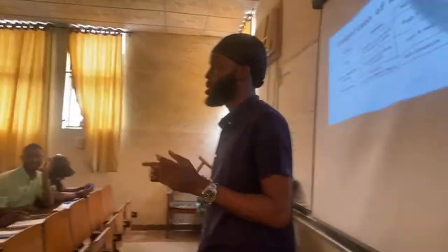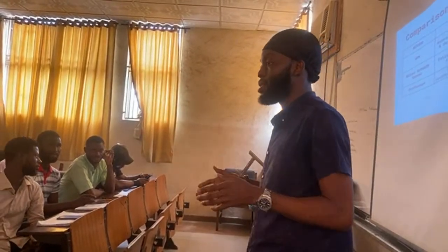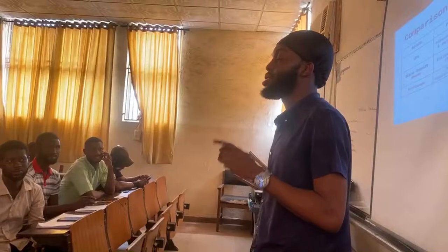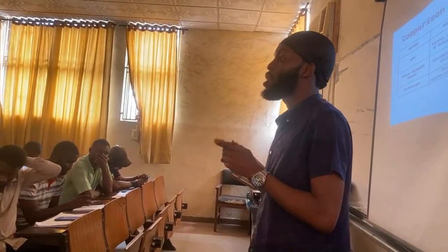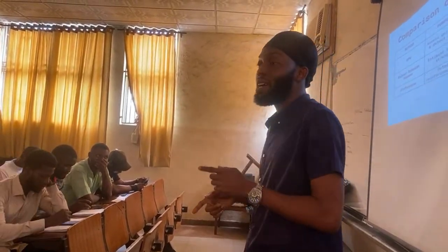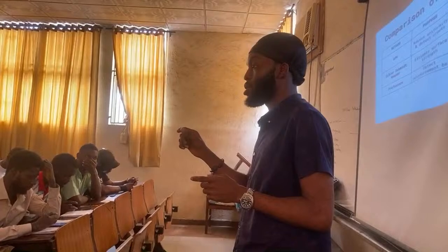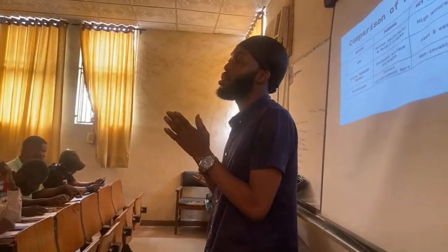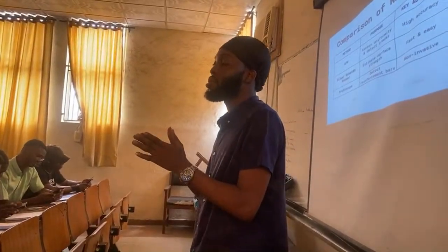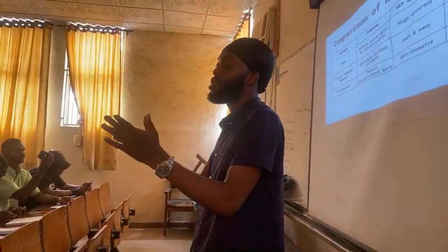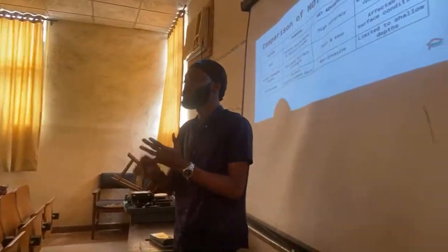Okay, the thing is this: whether the reinforcement is corroded or not, as long as it's there, you detect it. What you do not detect is the depth of the concrete or the size of the rebar. But when a metallic object, a rebar, is in a structural element, it will detect it. So let's say the rebar has corroded. You will know if a rebar has corroded from the visual signs on a particular structural element.